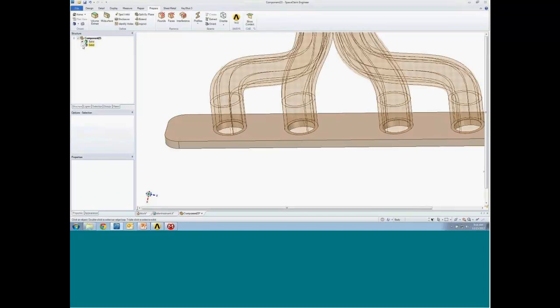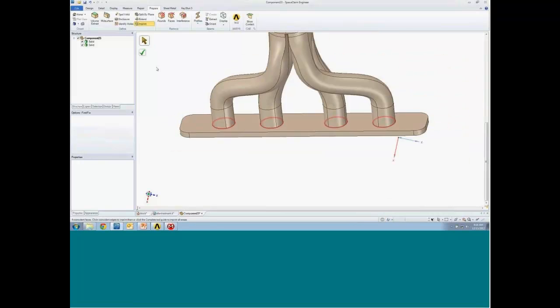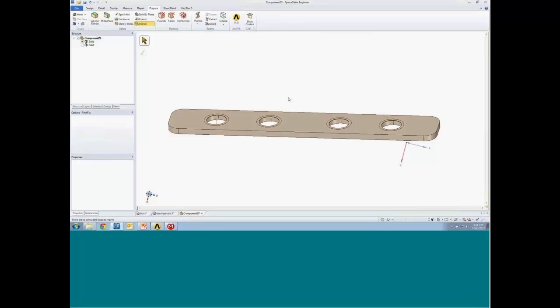Well, there's a tool that does that. I click a button, Imprint. SCDM will look through the model and find wherever there's an edge-to-face contact and identify all those locations, however many there are. And again, the great thing about these automated tools, you click a green checkbox, and then we'll go ahead and make the imprint from one set of edges to the face as appropriate. Okay. So that just worked its way through. We'll go ahead and look at the imprint. There you can see it clearly.